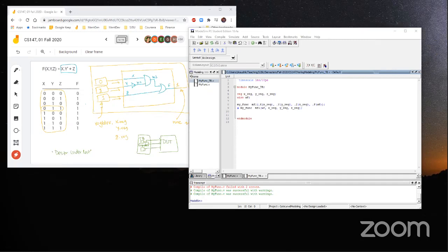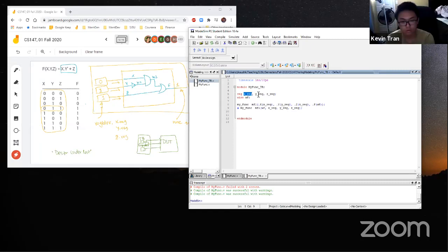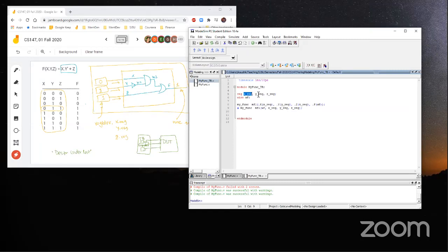Yeah, that's the implicit assumption that this X reg is connected to the port means logically there is a wire existing, and you can think of that wire name itself is X underscore reg. So you don't need to connect it register to the wire, then wire to the port. You don't need to do that. Thank you. Okay.